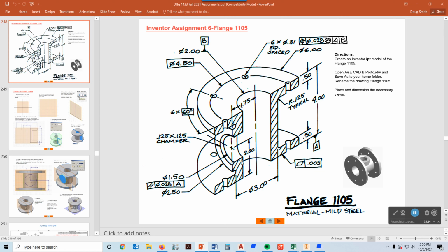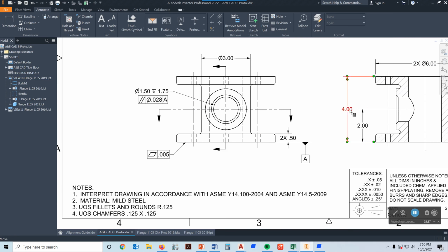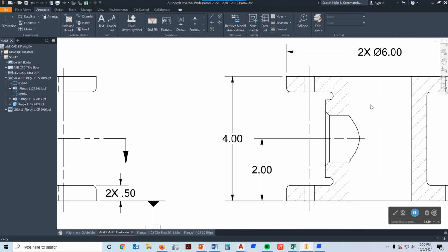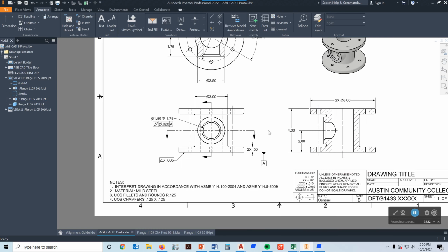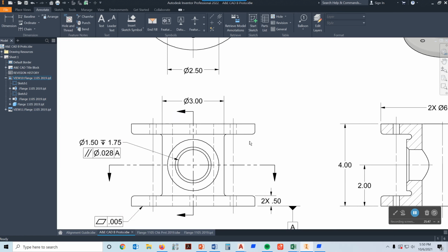And then all around this cylinder here, it's filleted. It is not filleted on the top edge, and it's not filleted on the bottom edge. So those are sharp edges. So we're going to go back so I can see there's my fillet here and a fillet there and so on like that. So those are my fillets, but not the bottom. These should be a sharp corner here, 90-degree corner, 90-degree corner on the top. And all those fillets will show up over here on the right side because they're modeled like that up here on the model.